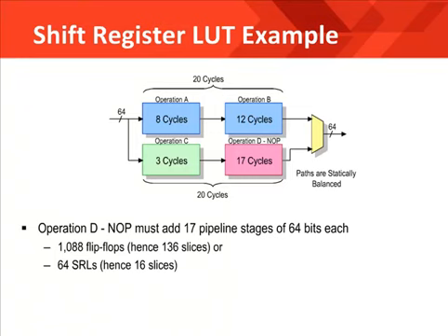Because there are so many registers in FPGAs, pipelining is an effective way of designing to increase design performance. Because pipelines can sometimes become unbalanced when too much logic must be generated, it is necessary to delay some of the signals. One of the best uses of the SRL is to add delay to balance those pipelines.